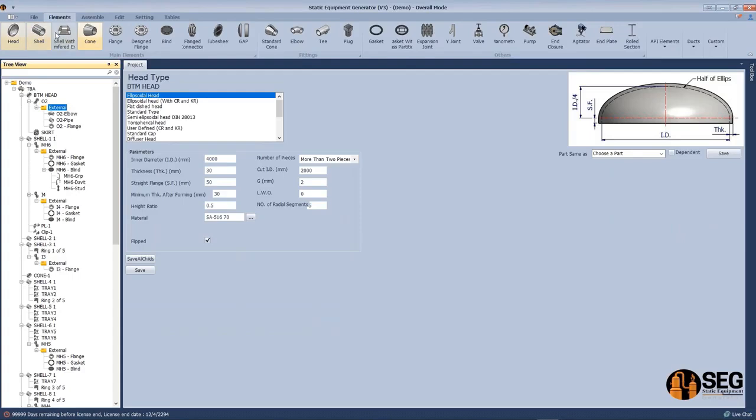elements here, you have the ability to add chamfered blades as a web or as a shell blade, concentric and eccentric cone from blade, standard flanges, designed flanges, blinds, different types of standard blinds, connection flanges, two flanges with a gasket automatically, tube sheets. If you would like to add a gap between elements, standard fittings like standard cones or standard reducers, elbows, T, plugs, gaskets with pass partition for heat exchanger, expansion joints, Y joint for heads.